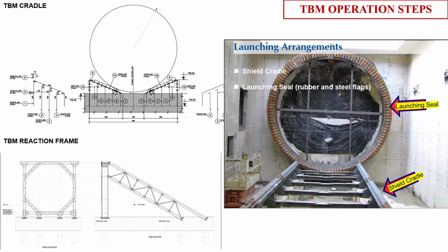Client also has their own land acquisition plan. Whatever the land acquisition plan, the client will give you that amount of land, because if you want extra land, then the client has to purchase that land, and it is not that he will get it, because if it is in a very dense area, it's not possible to get that amount of land. So in metro cities, it's not easily available. So mostly we rely on the launching of the TBM through a shaft.